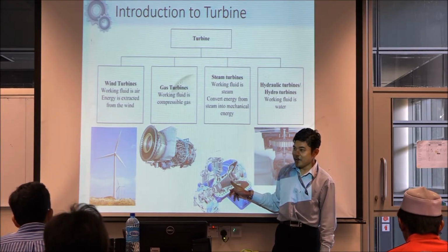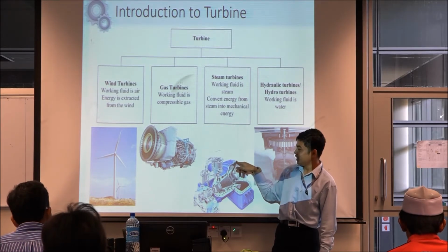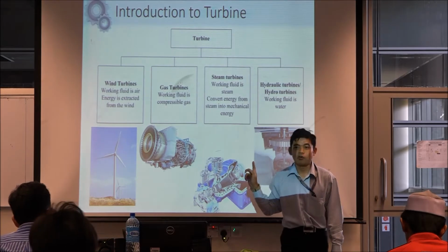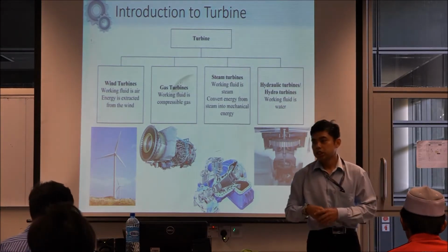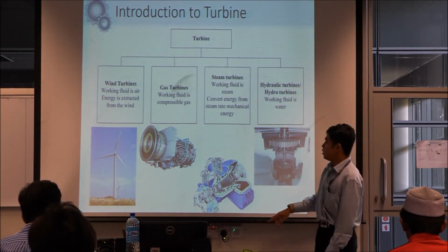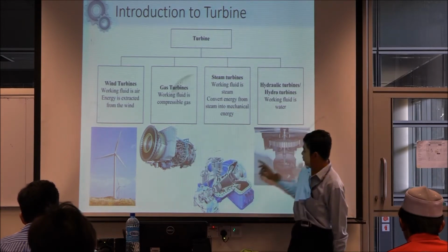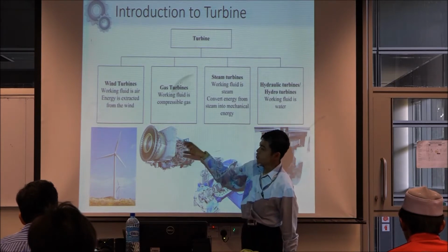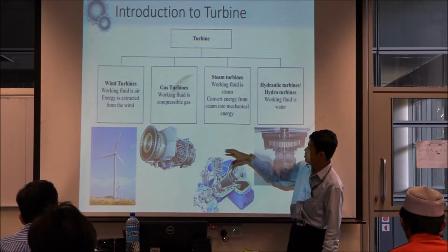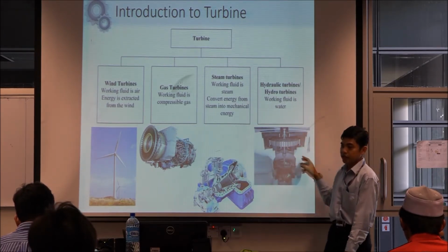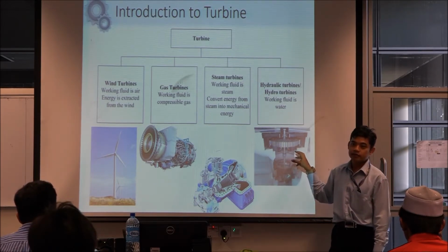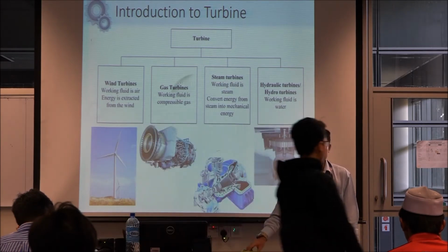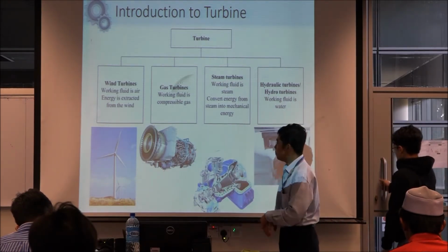Okay? Not enough, the exhaust of that can be used to make chilling water, like our GDC. So using an absorption chiller, you can have one, two, and the next system. So usually the gas turbine is used as the first one, then you have the steam turbine second, and then you have the absorption chiller after that. That's why nowadays the system is very, very efficient, because it uses the exhaust gas.